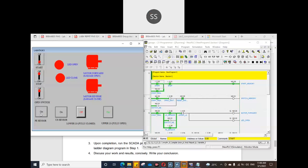Photoelectric sensor hit. So once the car has fully entered, the ultrasonic sensor also does not detect it, and the PE sensor also does not detect it because the car has fully entered. Okay, so now we can see the motor is reversed. Once the car is fully entered and there are no obstacles in between the garage door, the motor will start to close. When it starts to close, the upper limit switch is no more in contact, so it will reverse until the lower limit switch hits. So the motor stops. Okay, this is the first situation.